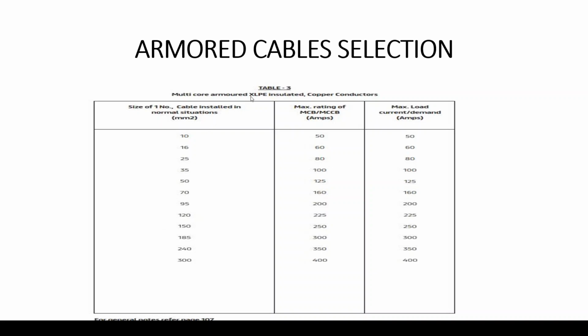Be sure to know which type of cable is specified in your project. If you have the choice, I advise you to use the XLPE. The increased cost for XLPE insulation is accounted for in the reduced conductor cross section which you are going to use, depending on the application. So in this case, I'm assuming the XLPE insulated cables, table number 3 in the DEWA regulations.